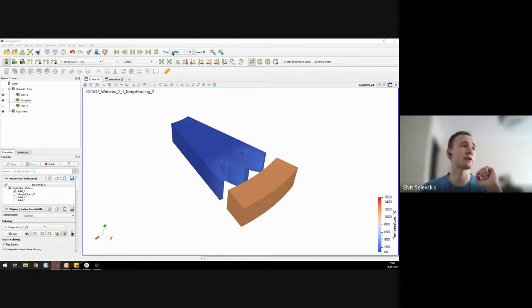Over here we can see the seconds, at which second we are, and here we can see the time steps going through. The buttons next to the play button are skip one frame, so move one time step, or move to the very beginning or the very end. In this case, the heating actually happens for 8 seconds in total. Here we are right around 6 seconds, and the heating is continuing up to 8 seconds.